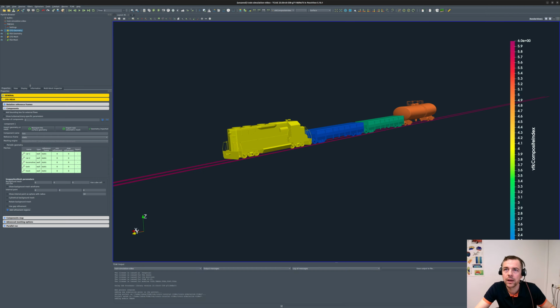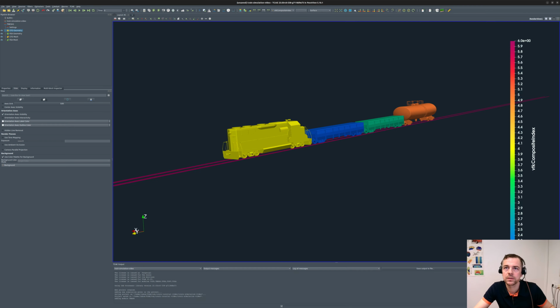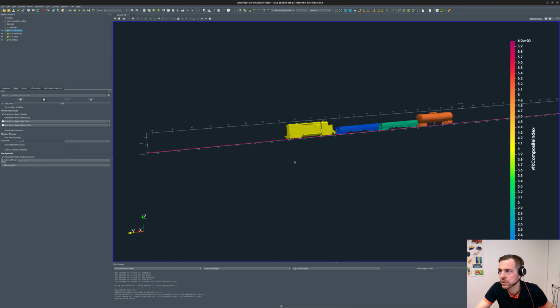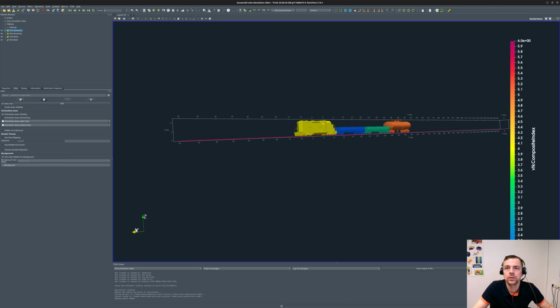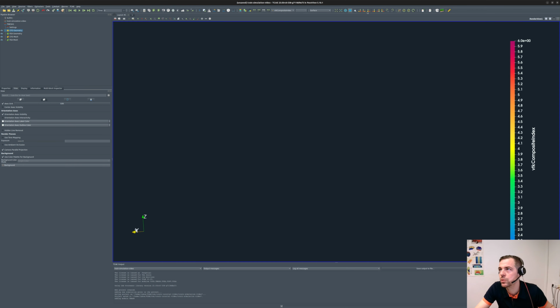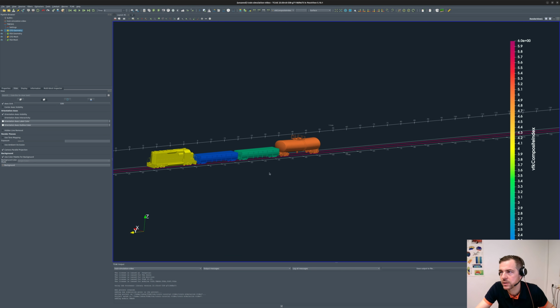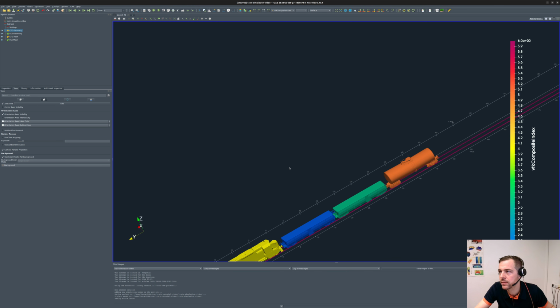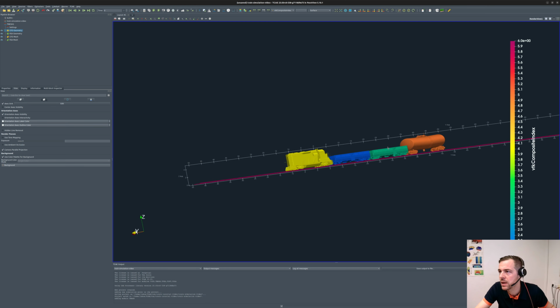Before I do that, I like to visualize a couple of things. I like to see the grid, to see the dimensions, and I usually prefer having the camera parallel projection in ParaView, which helps me to see things without perspective, because perspective for engineers sometimes is not doing a good service.